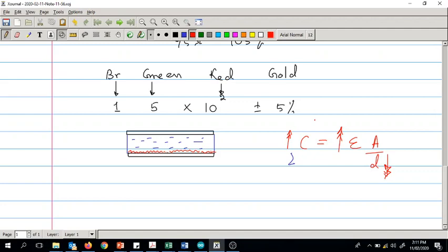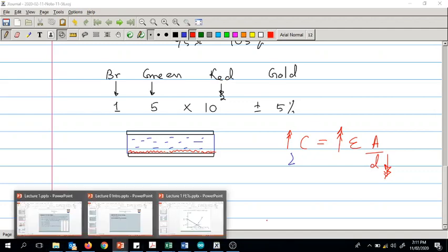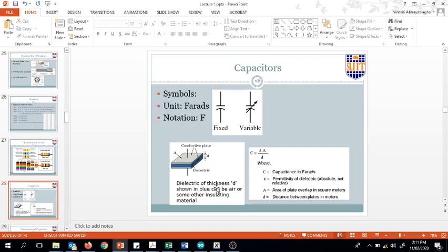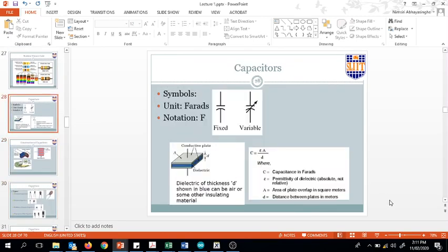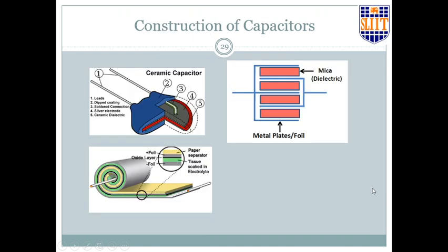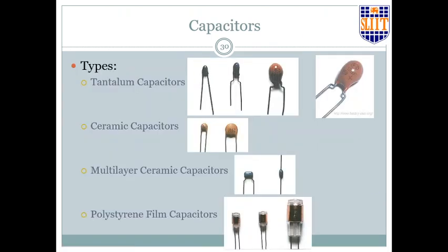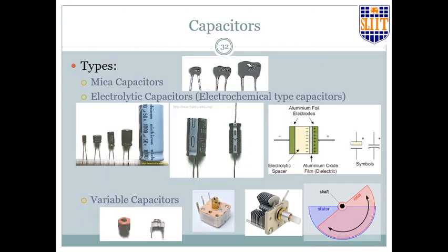So the electrolytic capacitors, however, need a correct potential to be applied across, right? That is why they actually have, if you can see here, a mark. This mark shows that side is your negative, this mark shows that side is your negative, and this arrow shows that this side is your negative. So you have to apply the right potential, like voltage, to get the capacitance working. If you suffer on the voltages, it will not work.